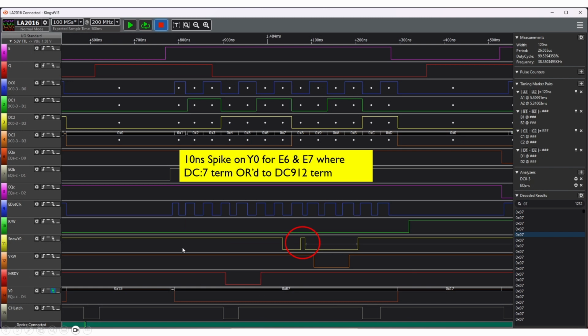Then finally, with some of the combinations, as I was having to separate out some of the conditions and rules for the various E0 to E7 signals, the E cycle was starting on a different CRTC clock cycle.